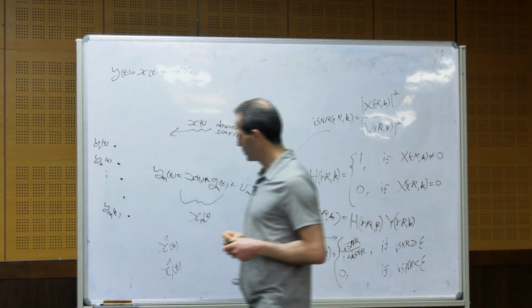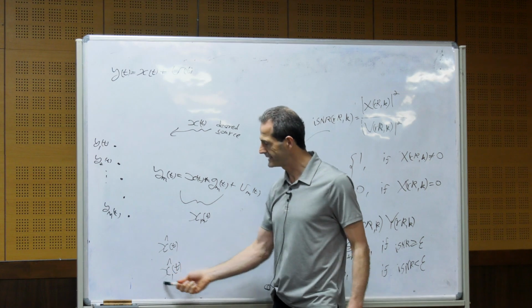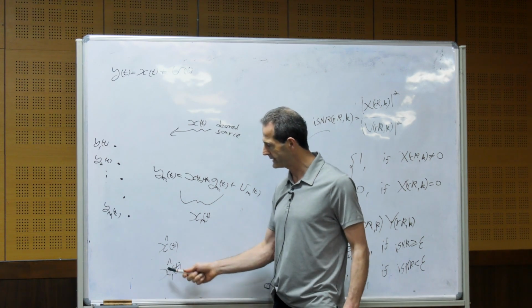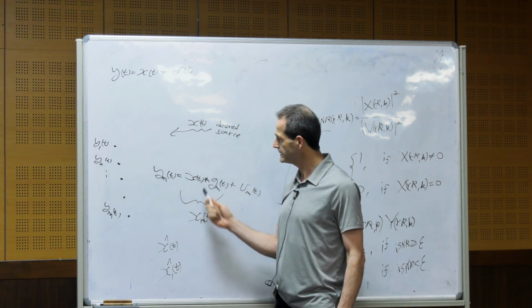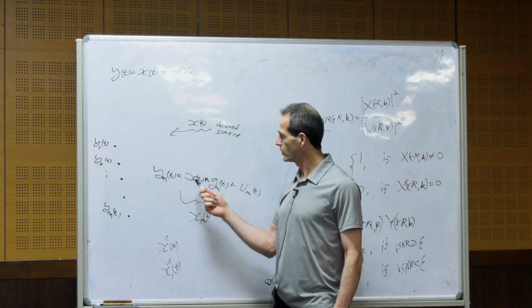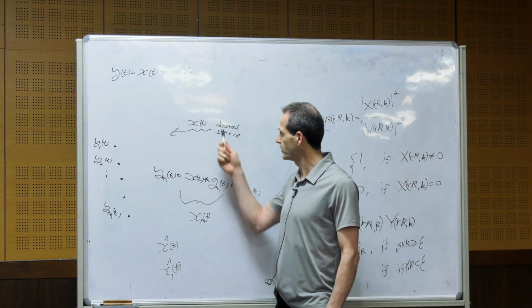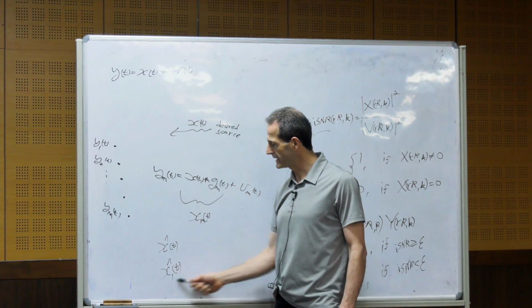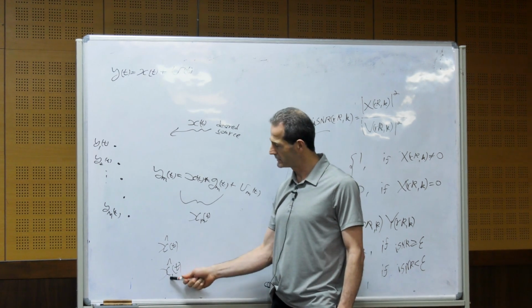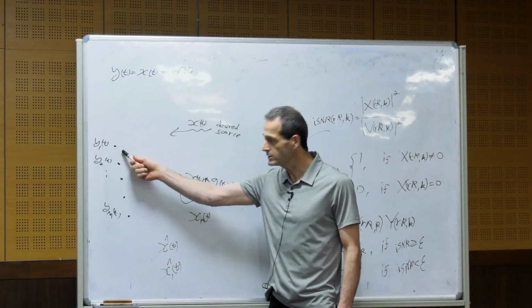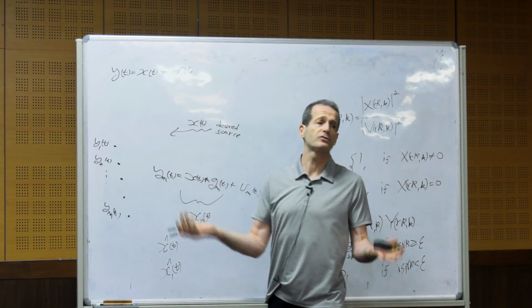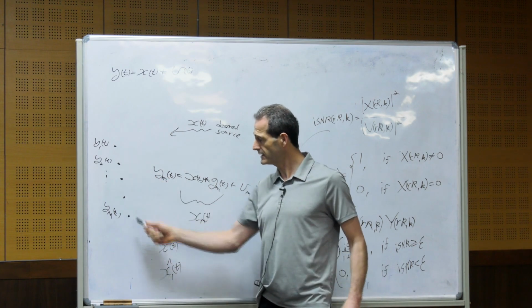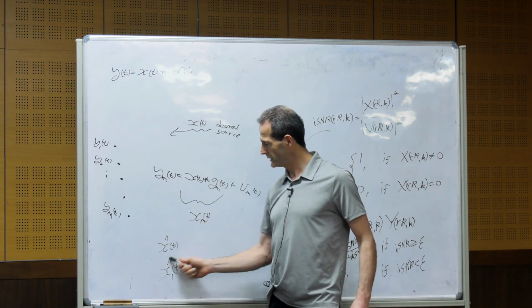Okay, so we focus on signal enhancement, only signal enhancement. So we try to estimate or to find x1t, which means that we find x convolved with the impulse response from the source to one of the sensors that we choose. Which sensor will we choose? The one with the least amount of reverberation, obviously. So we will use the other signals in order to estimate this.